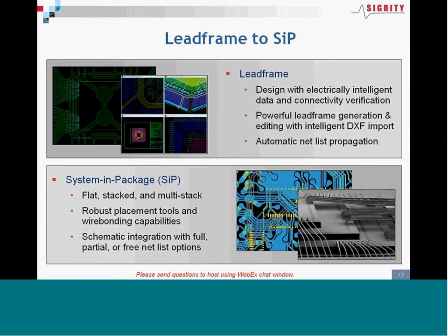For SIP, UPD supports a wide range of flat or stacked SIP configurations. The combination of our 3D environment and wire bond functionality makes UPD a very popular choice for this type of technology. We can also support mixed technology configurations where you may have a combination of flip chip and wire bond attachment technology all within the same package substrate.